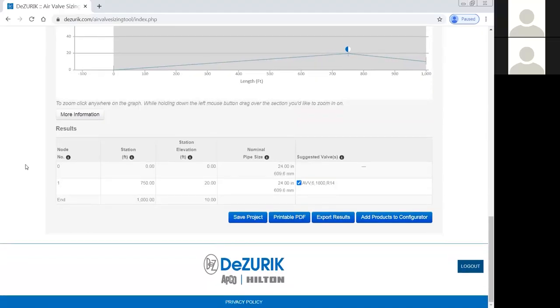Now, here's the result after you hit calculate. You get, similar to what the slide rule would have given you, a 6-inch air vac valve, body style 1800 with a 1/4 inch air release on it as well. So it's a dual body air vac valve. And this is usually enough. I could save this, I could print the document, I could send it to my customer, and it's usually enough. But sometimes people want to know more.